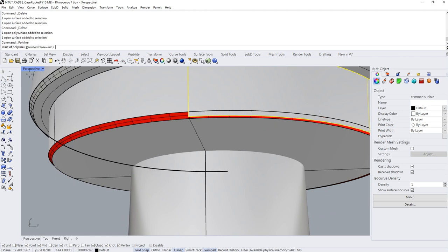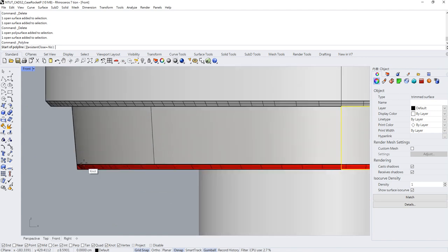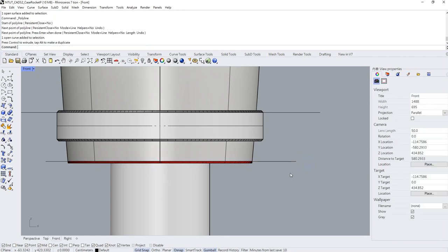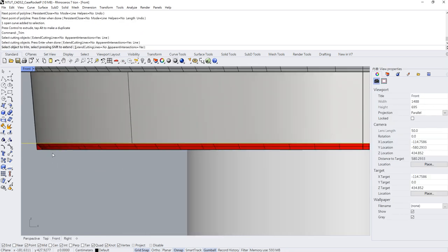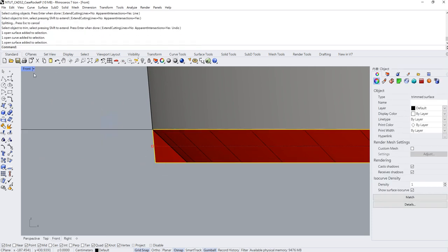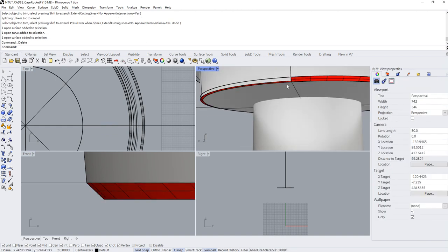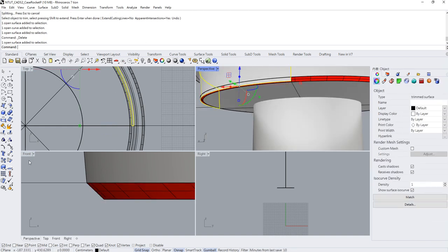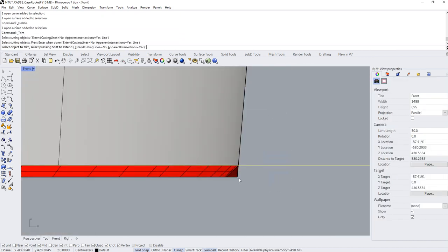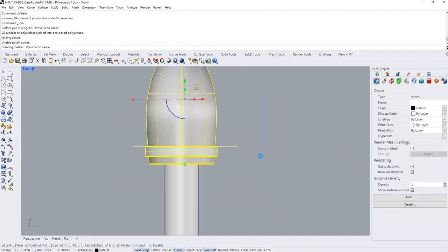So let's again go to the front view, hold your Shift key and draw a horizontal line, using this one as a knife. Ctrl T, choose the knife, and delete the surface. Oh, it doesn't work. Okay, let's take a look. Oh, for this part it actually works. How about this? Oh, that's the one which doesn't work. So again, let's make sure, it's about this part. Ctrl T, choose the line, and delete this part. So now everything is clean, and we can join them together.